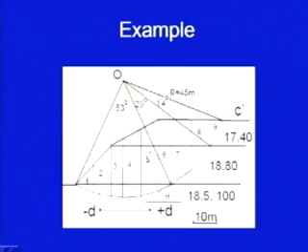Similarly, for example, the weight of slice number 5. Here you have to find this area. You find the ordinate number 1, ordinate number 2, and take their average. So, O1, O2, let us say (ordinate 1 plus ordinate 2) divided by 2, into this distance. This gives you area A1.